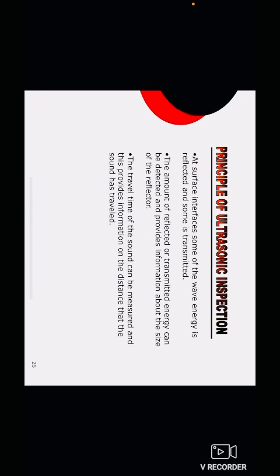At surface interfaces, some of the wave energy is reflected and some is transmitted. The amount of reflected or transmitted energy can be detected and provides information about the size of the reflector. The travel time of the sound can be measured and this provides information on the distance that the sound has traveled.